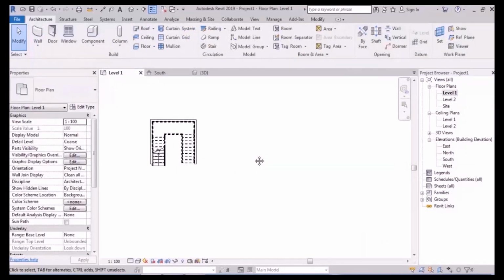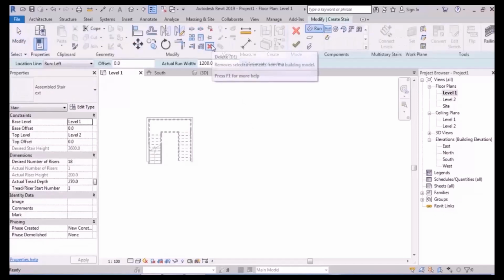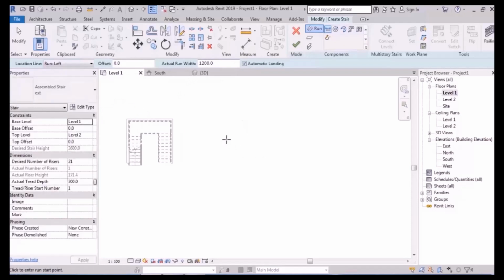Now, if you agree, let's go and see the different types of stairs. This one was a standard type of stairs with two ramps. And I said you need to create a gap between two rows of the stairs and also one riser ahead. Now, 3 ramp stairs. I select the stair, level 1 to level 2. The number of risers 21. Tread depth 30 centimeters, the width 1.20. I don't have any walls, so it must be right.